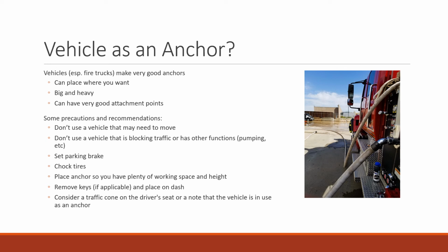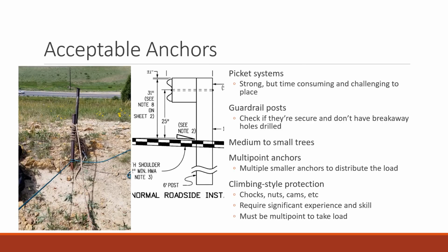There's also options like consider taking a traffic cone and putting it on the driver's seat to make it super obvious to anyone who's thinking, I'm going to move this truck, maybe I should think twice before moving it. Same with, you can put a note on the steering wheel, something like that. I've seen lockout-tagout kind of style things to put over the steering wheel. It can get a little wacky. Something to think about. Make sure that people won't move the truck inadvertently. It's your safety on the line, so take that extra time. Be a little bit overzealous there.